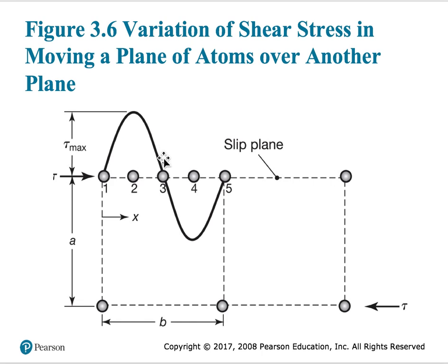Once these atoms start moving along the slip plane, if they go and hit up against a wall, they will stop. Similarly, the movement of atoms will stop after it has moved a certain distance. Then it will go to the next more suitable slip plane and slip direction combination. And once that ends, you go to the third one and fourth one and so on.